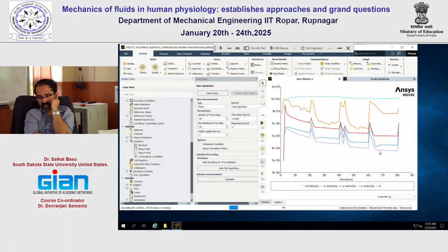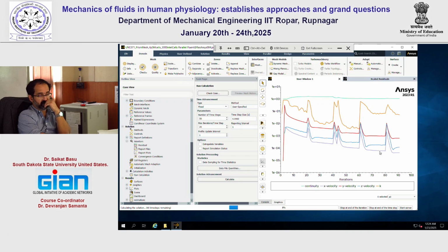But on the other hand, if you develop a two-phase simulation where the particles can impact the flow field, then you should probably think of it as a 5 second flow or a 2.5 second flow for the inspiratory cycle and see where the particles go with that. Because now it's a two-phase system, right? Does it make sense? But then again, the computing demand would be much higher. So something to think about in future.